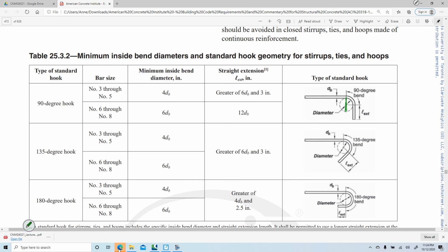We want our concrete, or our longitudinal reinforcement to nest in there as well as it can. So we're going to assume that the centroid of the corner longitudinal bars is at the centroid of this diameter.